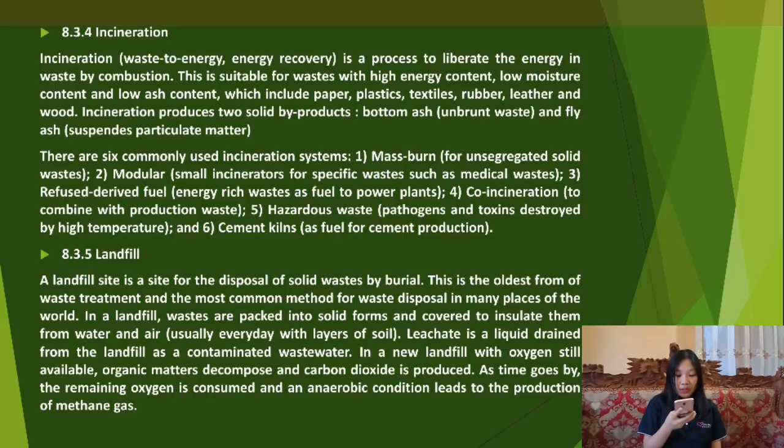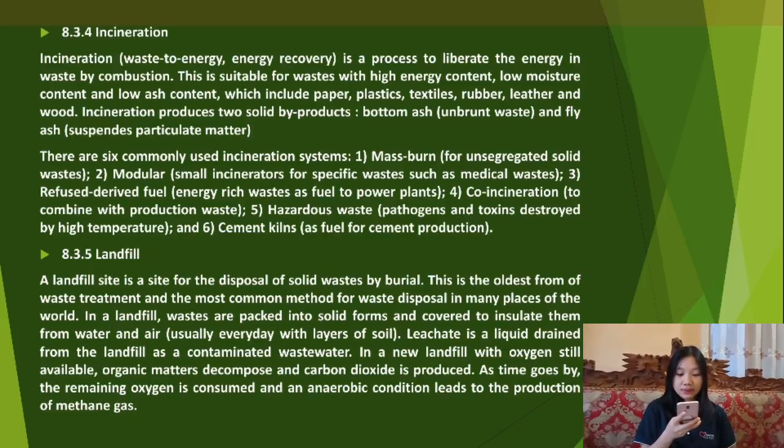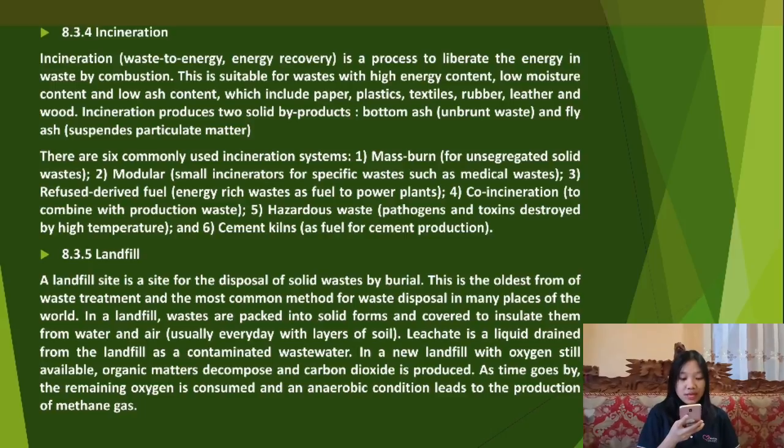Incineration produces two solid byproducts: bottom ash, unburned waste, and fly ash, suspended particulate matter. There are 6 commonly used incineration systems. 1. Mass burn for unsegregated solid waste.